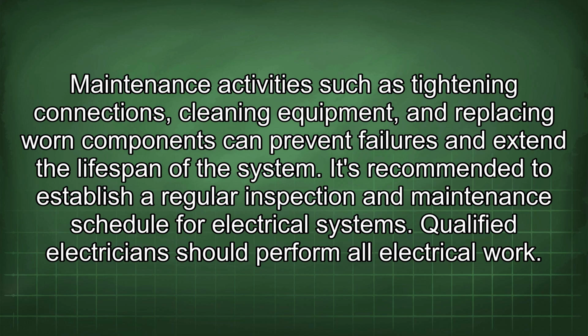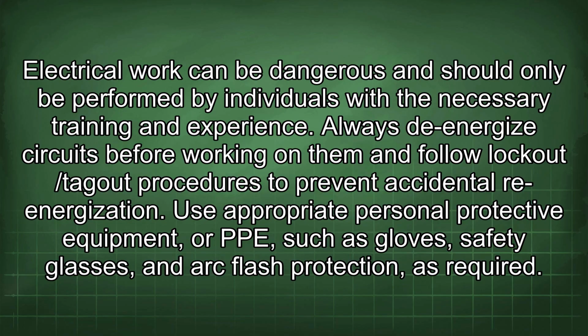Qualified electricians should perform all electrical work. Electrical work can be dangerous and should only be performed by individuals with the necessary training and experience. Always de-energize circuits before working on them and follow lockout/tagout procedures to prevent accidental re-energization. Use appropriate personal protective equipment, or PPE, such as gloves, safety glasses, and arc flash protection as required.